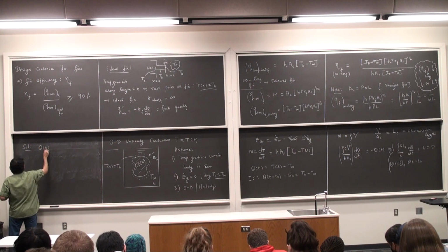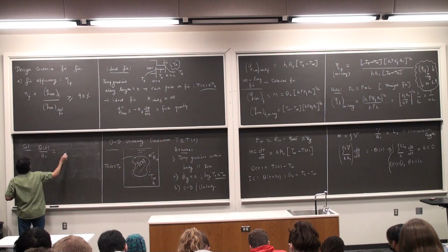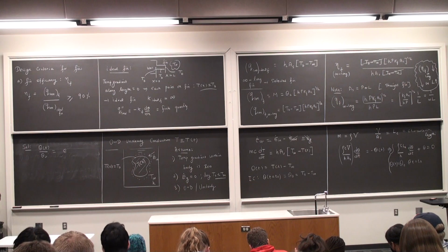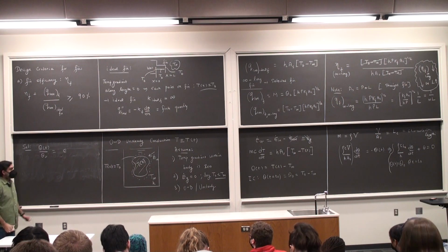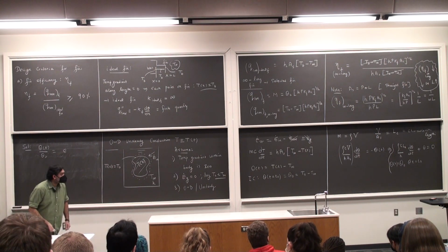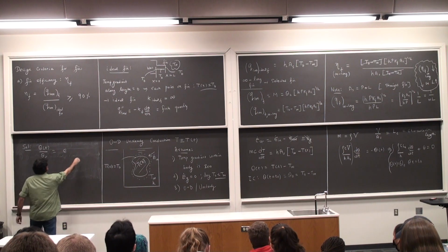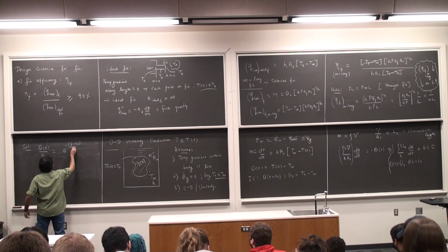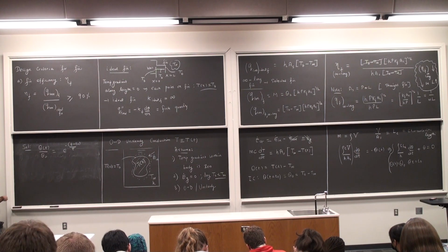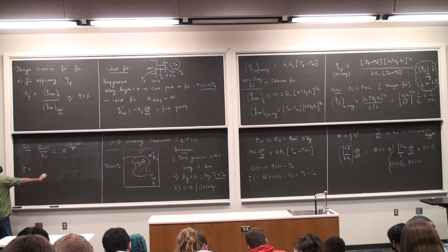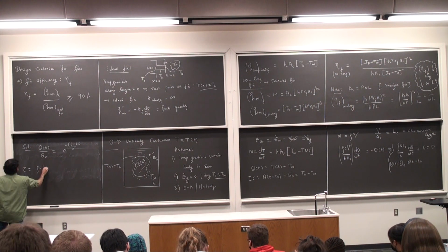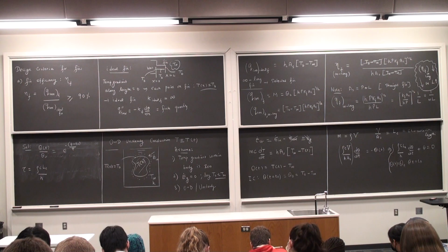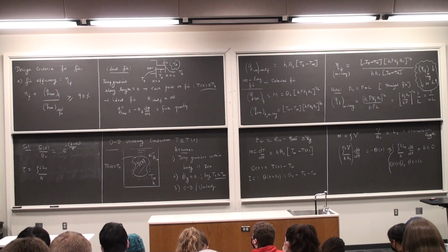Theta by theta naught is e to the power, and I'm going to call that character there, rho c L_c by h, as tau. So this is going to be minus (t minus t naught) by tau, where tau is rho c L_c by h. Let's unpack its units. Okay, let's make sure that this is indeed a time constant. It has units of seconds.